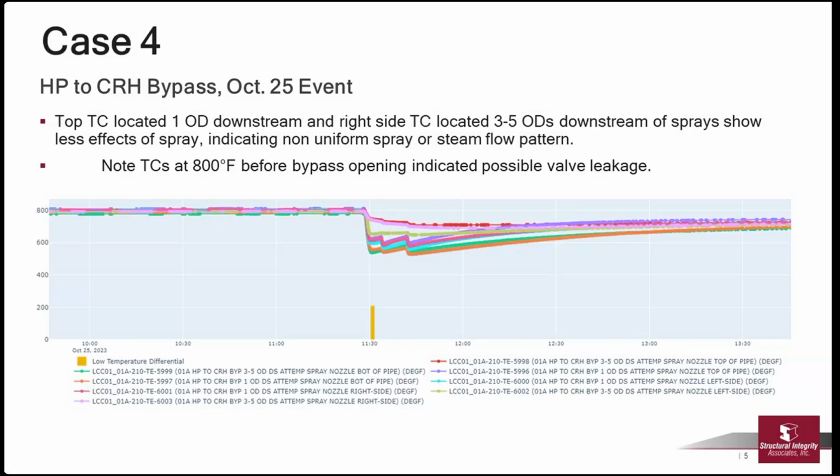So the monitoring system, besides pointing out excursions and variations, can also give you other interesting information, such as this: that your valves are leaking. And I've seen this on several units where you expected to have your pipes sitting at ambient, and they're running much, much hotter. The far downstream thermocouples, the thermal wells, could be hundreds of feet away from the valve, so even if you got some bypassing steam, by the time it gets down there, a lot of it has cooled off, so you're not really getting a good feel for that with your plant instrumentation.